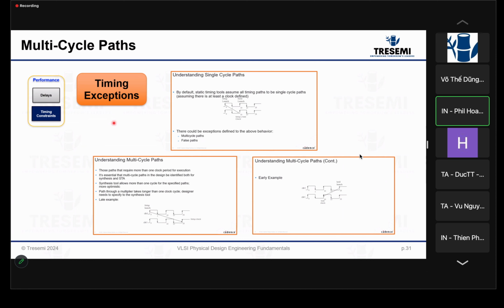You can set multi-cycle path 3, 4, 5, depending on your logic design. And that is for the setup. Typically, because your chip is slow, and for certain parts of your circuitry the chip is slow, you want to be able to meet the speed by specifying multi-cycle paths.